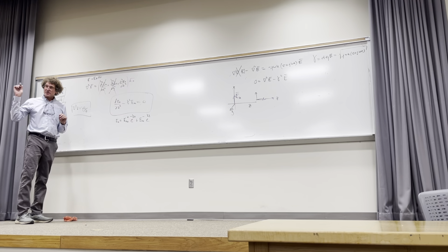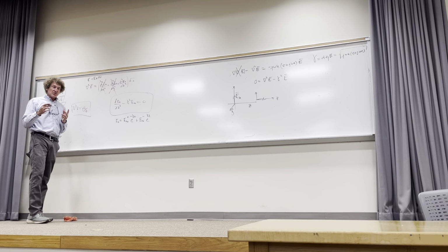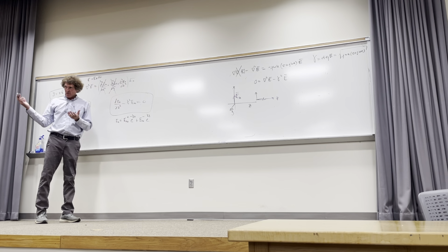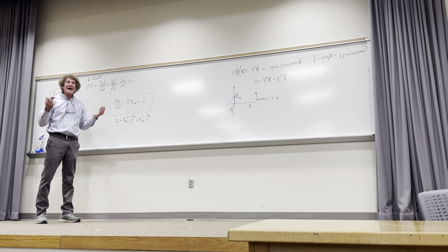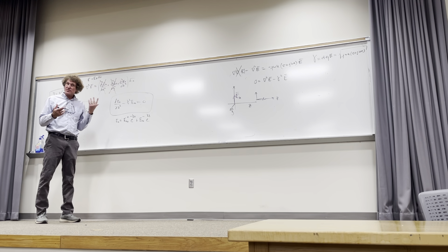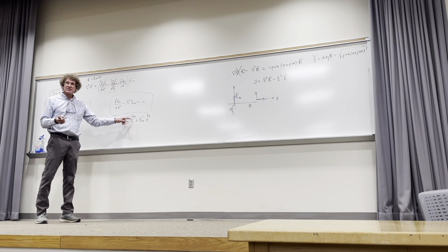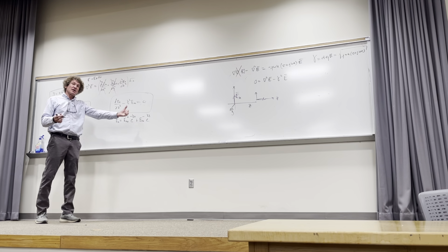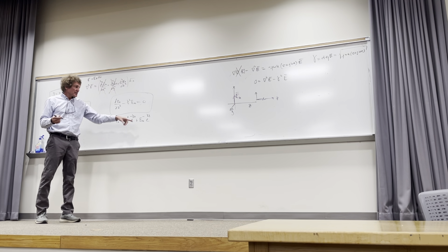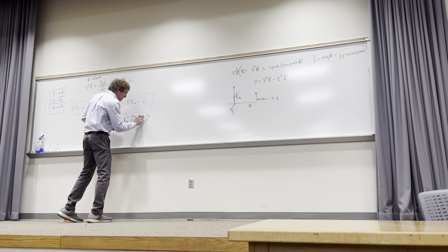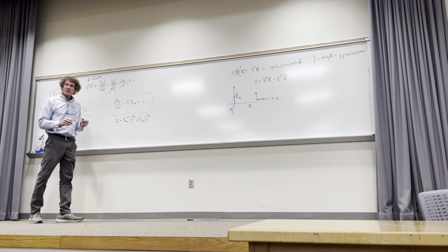This looks exactly like propagation on a transmission line. You remember, for a transmission line, you have some V0 plus, and then you would have e to the minus gamma z, and if it was lossless, it would just be e to the minus j beta z, right? Plus some negative going wave times e to the plus gamma z. So this E minus thing just means it's the negative. That's the general solution.